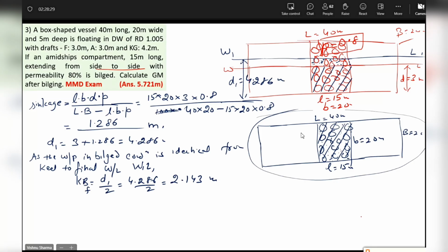On the center line, okay. It would be exactly here. Yes or no, beta? Correct. Why? Because for this area it will be here. For this area it will be here. For this cargo area it will be here. The combined geometric center will be here. So this will be the center of flotation, and I draw a line that coincides with the center line.